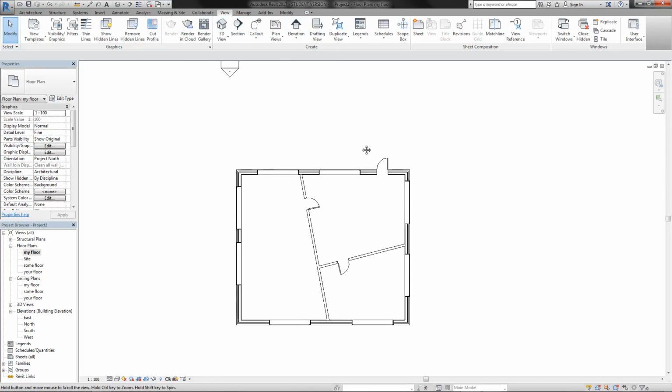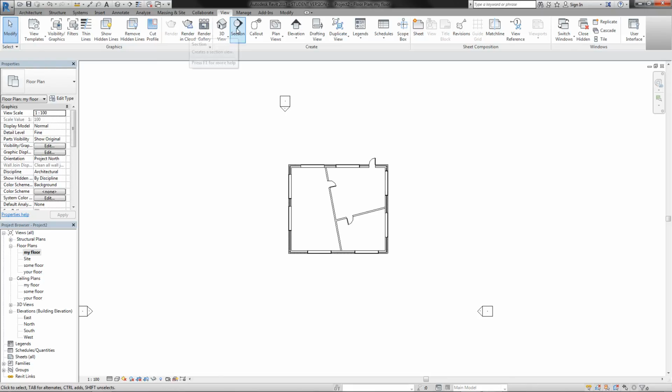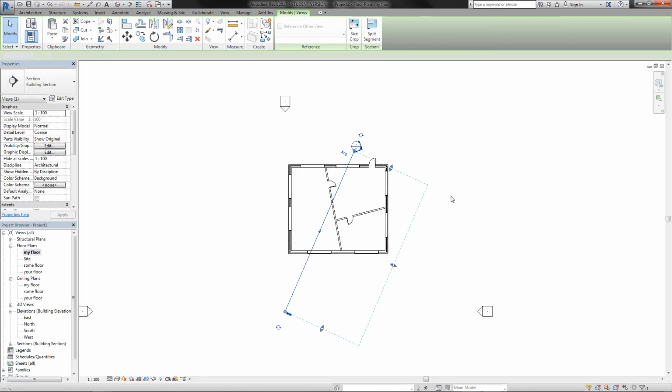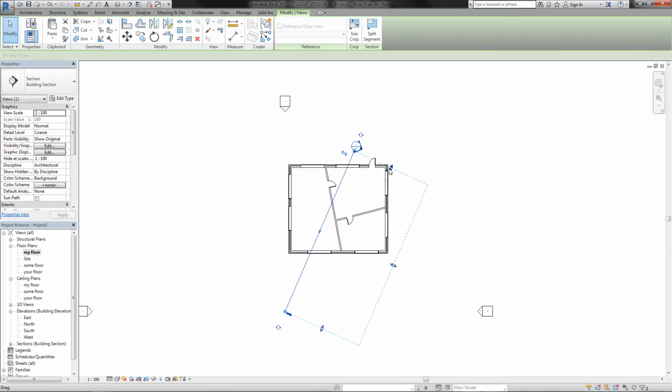Things I said be cautious about deleting. Those guys are basically just elevations. I want to draw a section here that is going at an angle like that. As you saw when you select this, it will give you this box. So anything inside this box is what I see. I can flip it by clicking on those arrows. I can even say, hey, I don't want to see back there, cut it, or I don't want to see this corner. This will cut it for you.